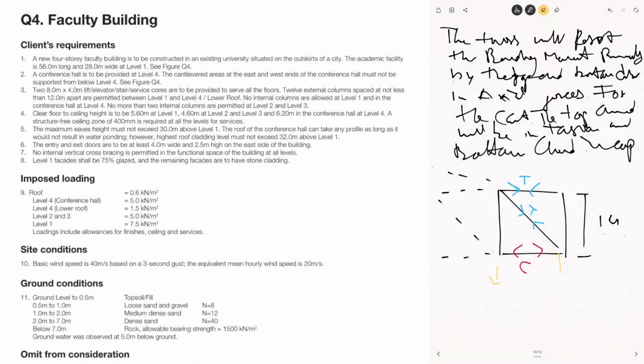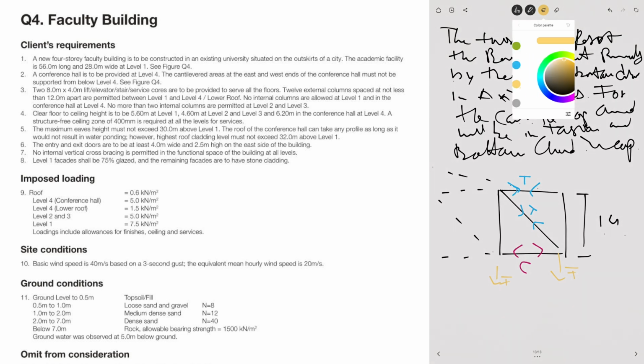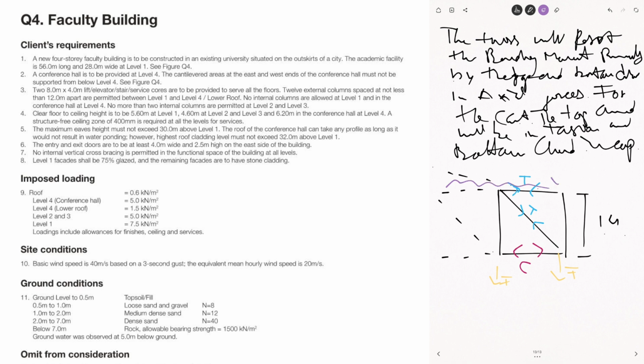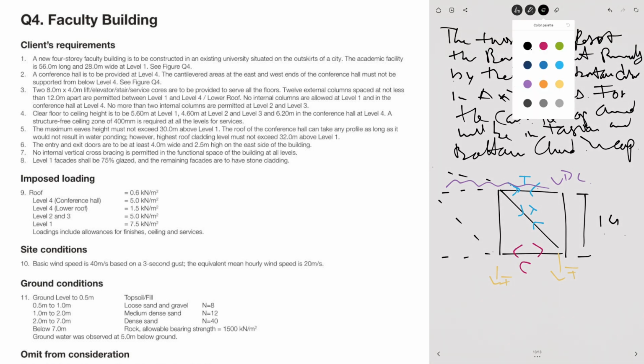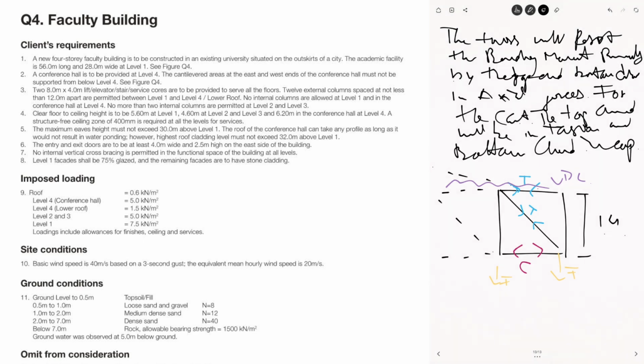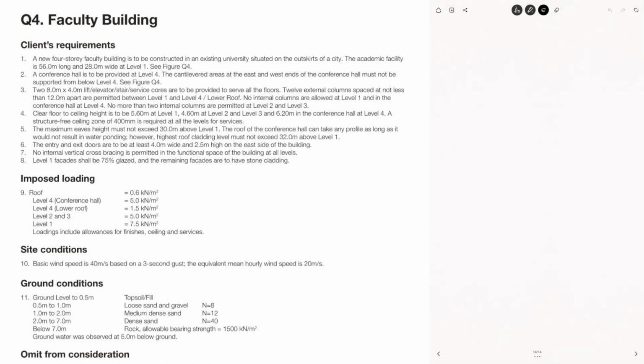And we have our UDL applied. Well, we got the forces here, so force F, F, and our UDL applied on the top. Okay. Once we know that, and we explain that this is basically how it is behaving, and that the bending moment will be resisted, I didn't draw the bending moment. Bending moment will be resisted by the top and bottom chords. Then we can start going with the actual calculations of the steel truss.